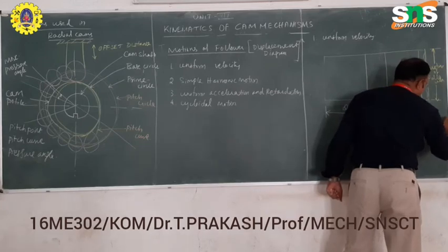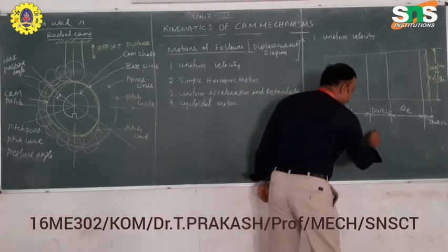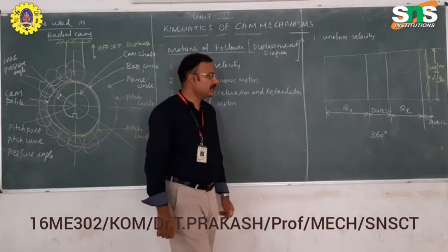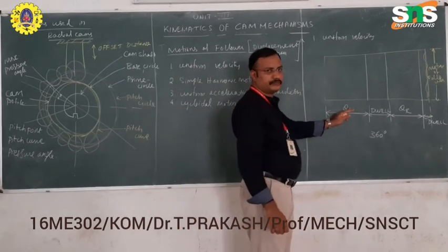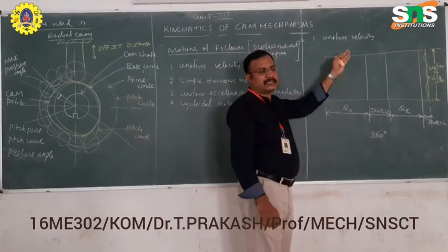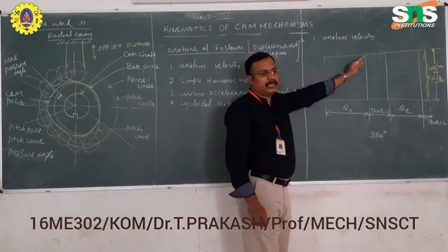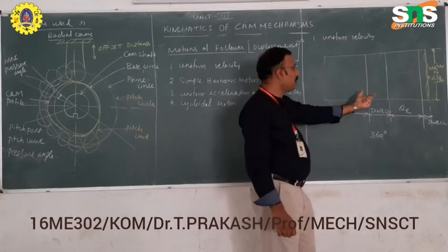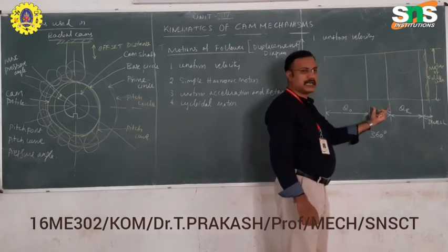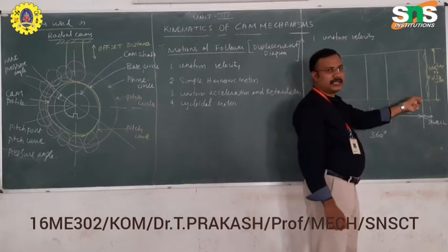The total angle taken by the cam will be, since it is a shaft, 360 degrees. They will give some outward stroke where the follower will have some operation from opening conditions. For example, in IC engines, the valve will be in open condition. The valve will be slightly opening during the outward stroke, and in the dwell period there will be a rest period. The valve will be open at this angle of the cam. Then in the return stroke, the valve will be closing.